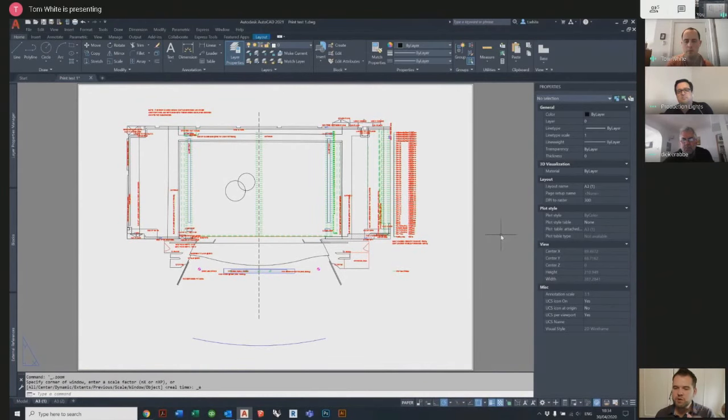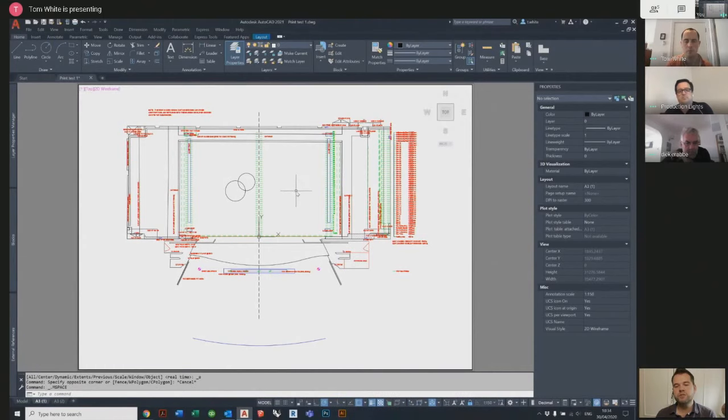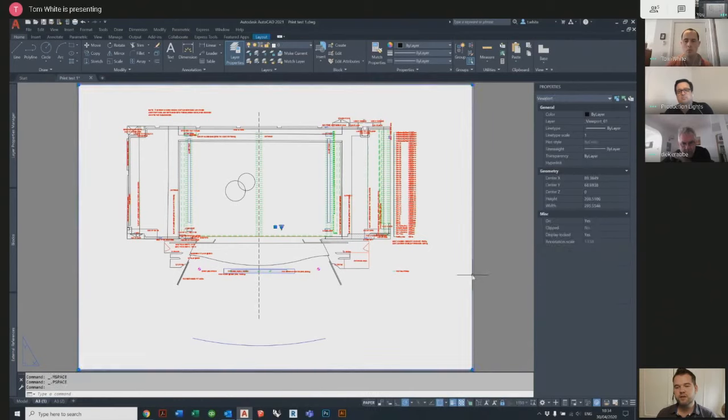And Tom, if you just double click into your model space in this paper space view, you still don't see that frozen layer. It is switched off there, even though we've now double clicked into model space. So you can change other things in that drawing, but it's much more tidied up. So yeah, Dick, you could just, for example, look at your sound and the flybars and the basic building, because that might be the level of detail that you need, or you might need a power layer turned on as well. But yeah, you could really get rid of a lot of that superfluous stuff.